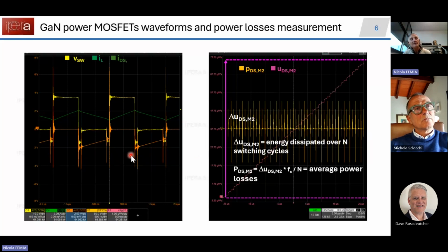And finally, you must be aware of the impact of some insidious problems like the deskew of probes. That is very important in order to reconstruct the peak power waveform that can be, for example, integrated by an oscilloscope to get the energy graph, and then measure the right value of the power loss.